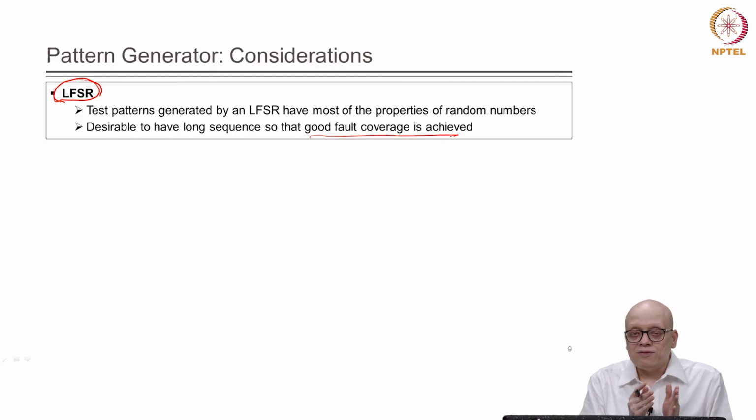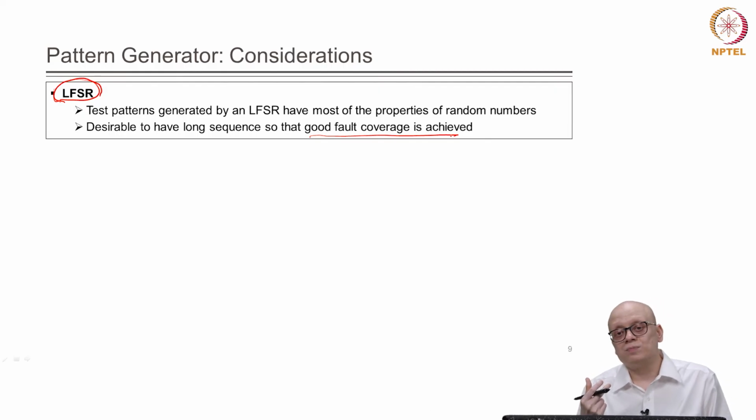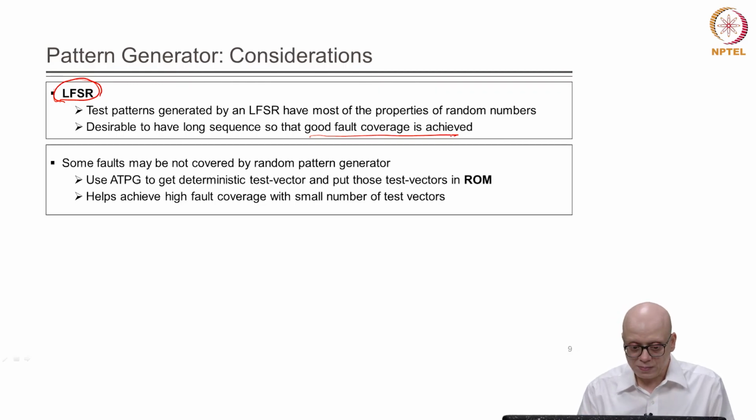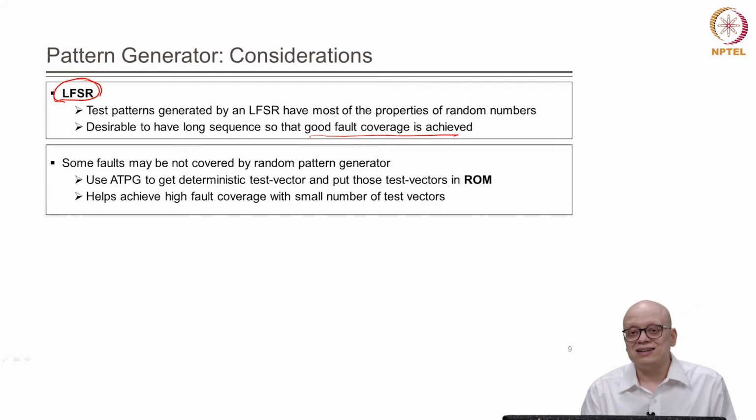Then if we have a sufficient number of state elements in the LFSR, and also if we choose the feedback function properly, then we can have long sequences of random test patterns generated by an LFSR. However, some faults may not be covered by a random pattern generator.